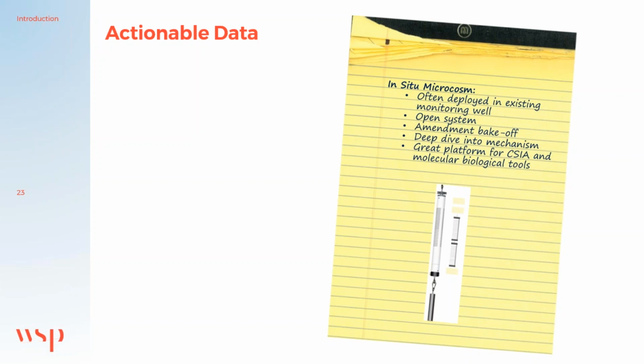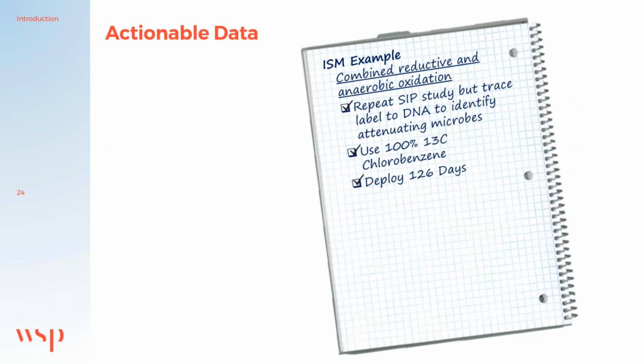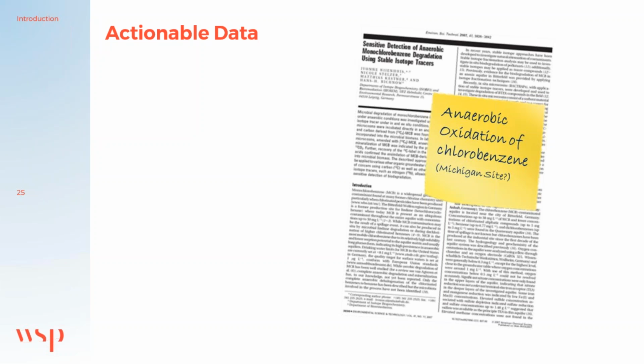We performed this study at the same chlorobenzene site that we just discussed, after the bench test failed small. But first, a bit of background. After the ISCO failed, we turned to a bioremediation remedy. Bio for chlorobenzenes can get a bit complicated because it's easy to reduce tri- and dichlorobenzenes to chlorobenzene and benzene in anoxic environments. But treatment of these daughter products, especially chlorobenzene, is typically performed in aerobic environments.